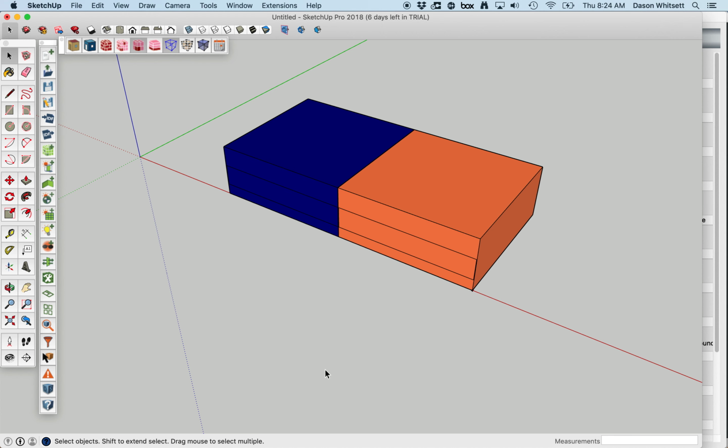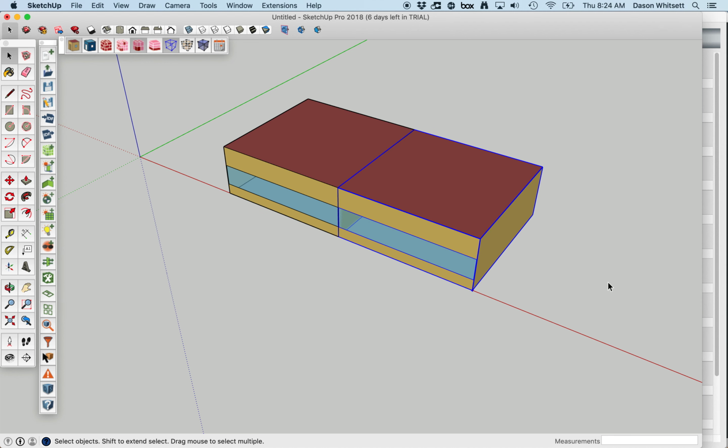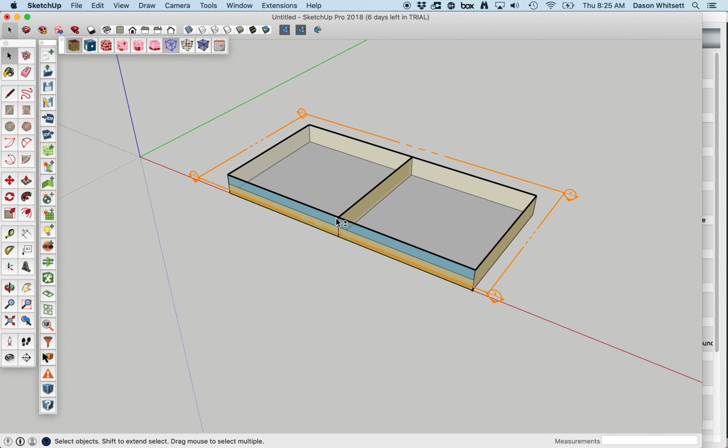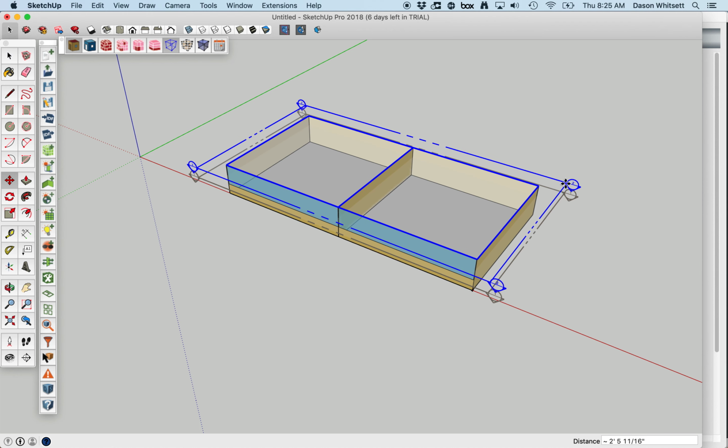So the first thing we'll do is put in an illuminance map in the zone that we want to assign the daylighting to. We're going to use this zone here on the right. One thing that's really helpful when you're working with daylighting is to use the section tool from SketchUp. I've selected that here. I'm going to hover until it turns blue so it's horizontal, hold shift so it stays horizontal, and then click within my space above the level that I'd like my illuminance map to sit at, and then cut my space. In fact, I'm going to move that up just a little bit to make sure it's above where my illuminance map goes.